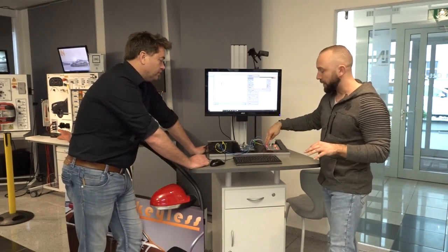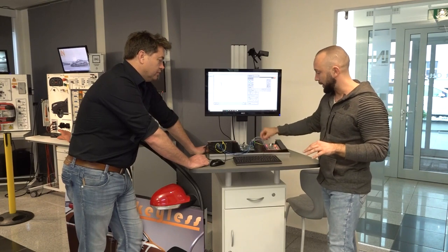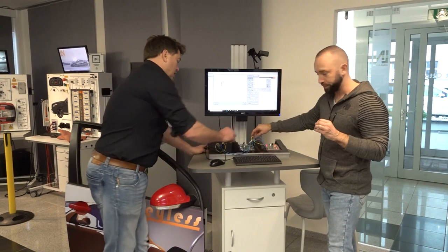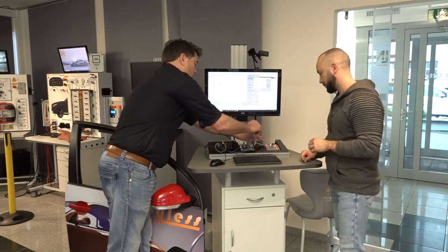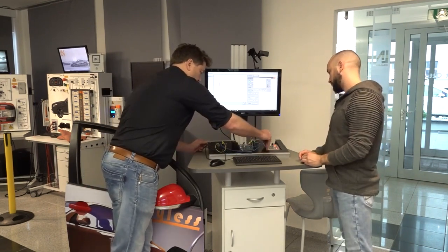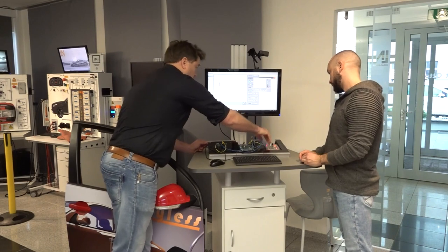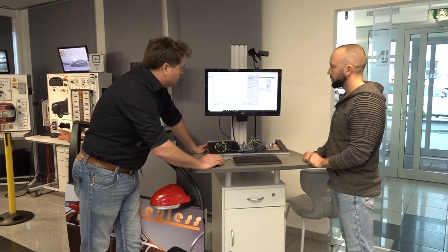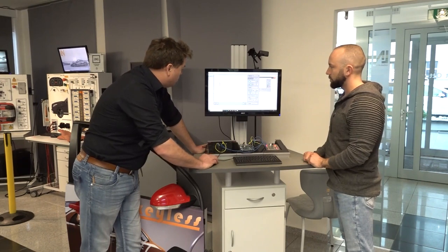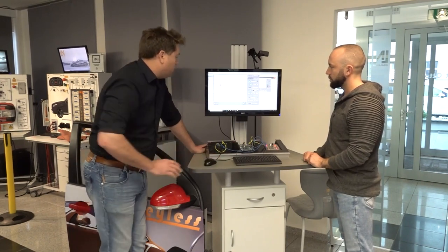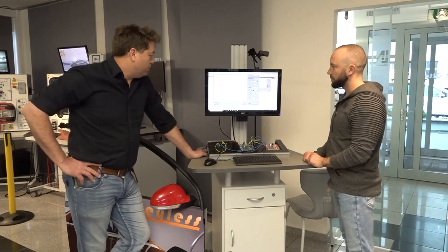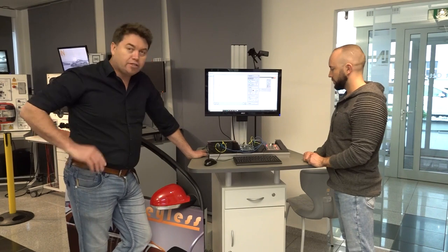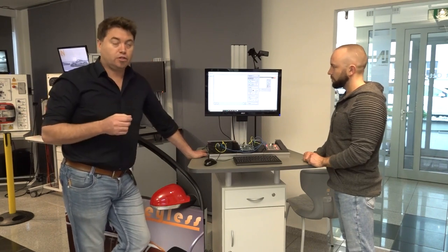But when we would measure on the other side, where the cable is gone, you would see the difference in the signal. And that's where it becomes very important when it comes to measuring. So we can put that into a CAN mode there. Now it's gone. We might have to get a bit creative with our oscilloscope usage. This is where it becomes vitally important to understand how to use an oscilloscope.